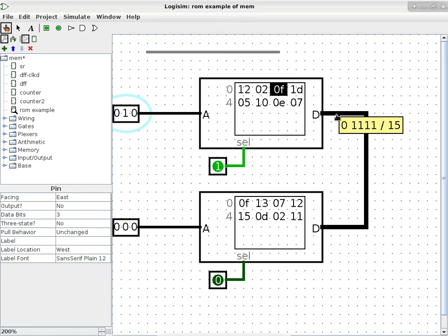Cool. So I'm going to throw a wrench into this whole thing, turn this back into 0, and then look at this wire again. This is -14. Why is it -14? It's looking at the 5 bits as a signed integer. It's a 5-bit signed interpretation. Okay, the most significant bit is always the sign bit. Is that okay? So we have 1, 2, 4, 8, and this is specifying -16. So we have -16 plus 2, and that turns out to be -14. So it does make sense, okay?